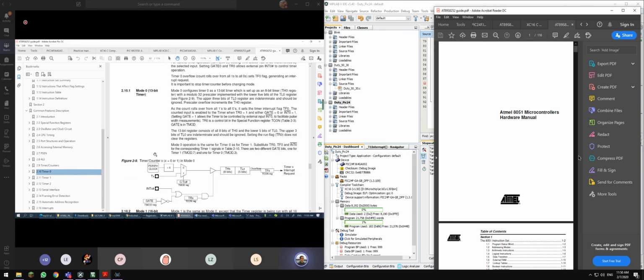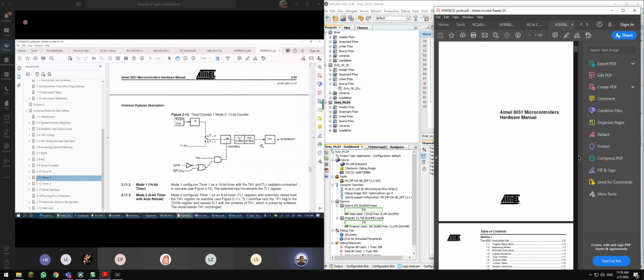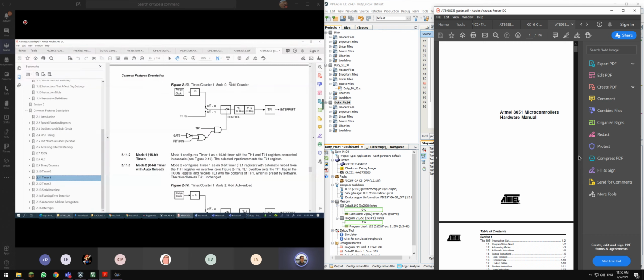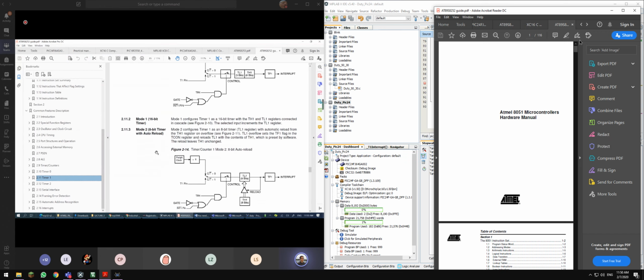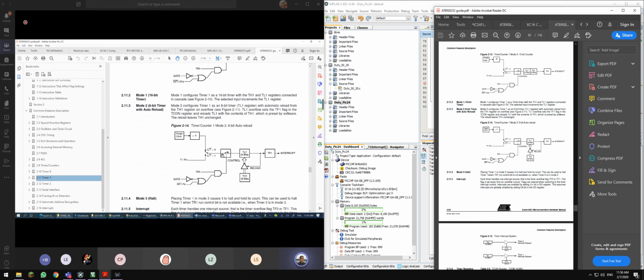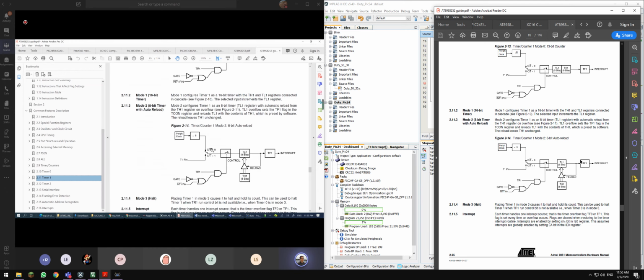Yeah. So let's use timer 1 now. This is timer 1. It has a 13-bit mode, but we are now using 16-bit mode, exactly the same as PIC18. The interrupt here is an external interrupt. There's a pin here for counter or timer. If you choose timer, we set it to 0. If you choose counter, you set it to 1. You can see from here: choosing 1 means you choose this, choosing 0 means you choose this.